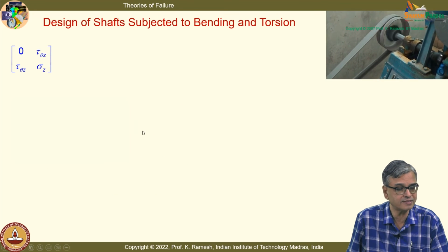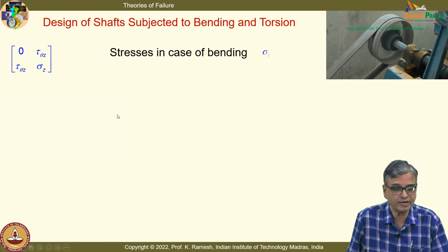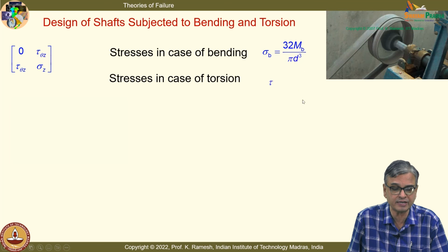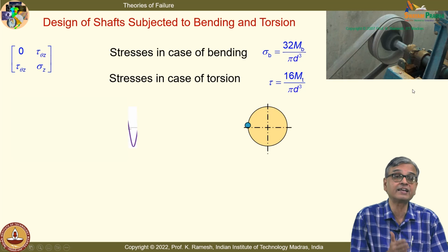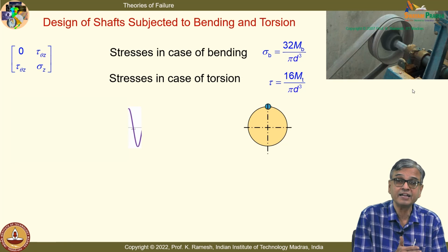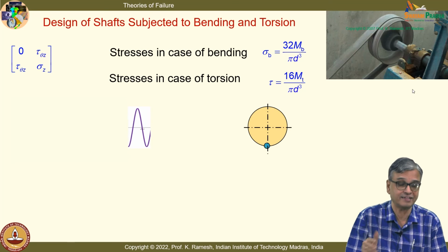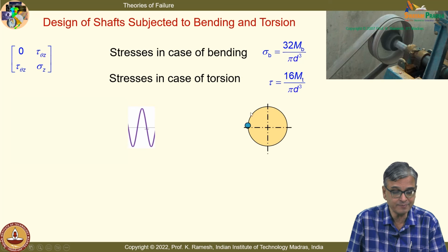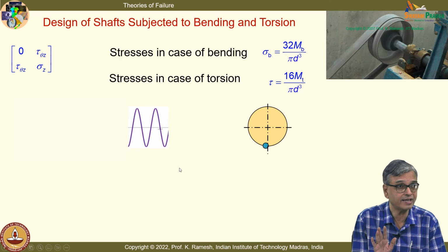So, when I have the stress tensor in this form, in the design courses they simply express it in terms of the bending moment and twisting moment. And because the shaft is rotating, you have to recognize that the bending introduces stress that varies cyclically, because this shows how the fiber experiences load due to rotation, which is a very subtle point. Okay. You may miss it.